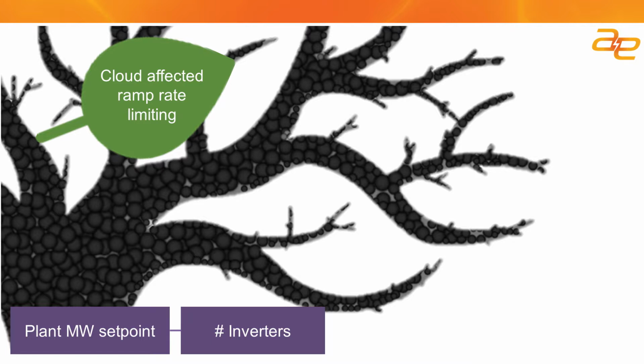So not only do we need to ramp the site output up and down in an orderly fashion, 10% per minute, during normal conditions, but also if a cloud were to come and depart from the site, you need to ramp the site back up from the lowest output due to clouds at that same 10% per minute. And it's not at all straightforward on how to do this.